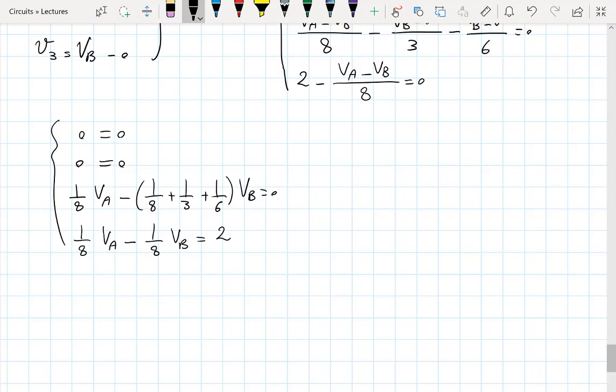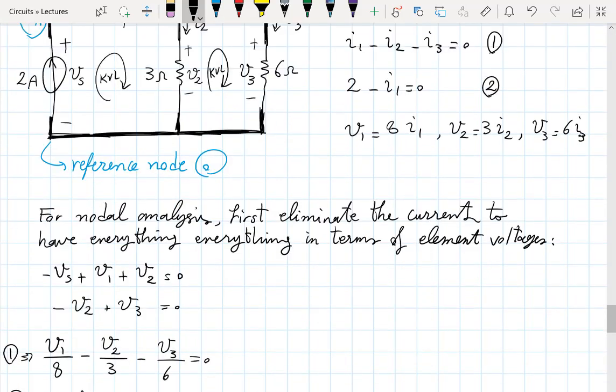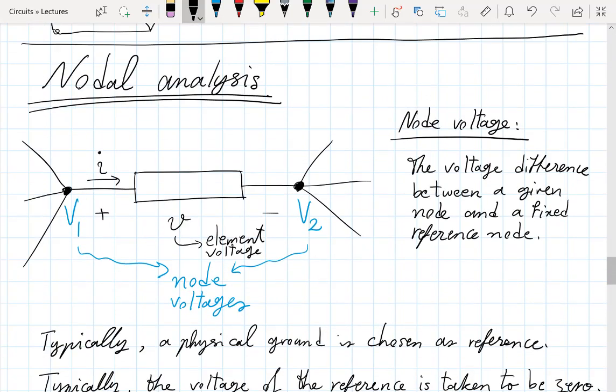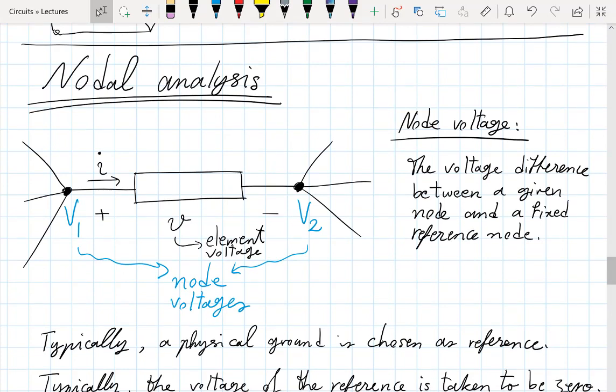So it's not that KVL does not exist or is trivial or obsolete. Not at all. The way KVL entered our equation was by this very definition up here. This thing that I said, this little v equals v1 minus v2, is KVL. Because imagine, this v1 is the voltage difference between this point and some reference here.